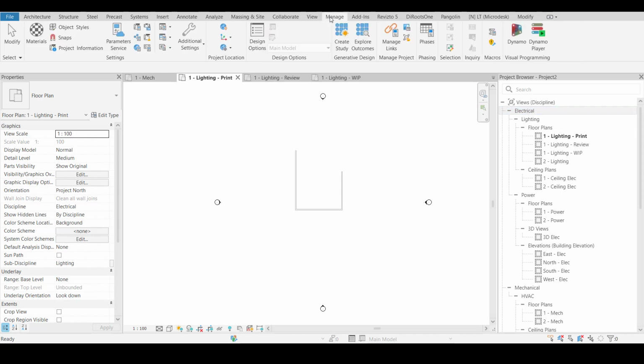You only have to learn this item for this particular use case. As I said earlier, we will not learn the complete set of tools, we will learn how to perform one task by a combination of the tools. So we are going to create one parameter which will be applicable to views and can be used to organize our views.